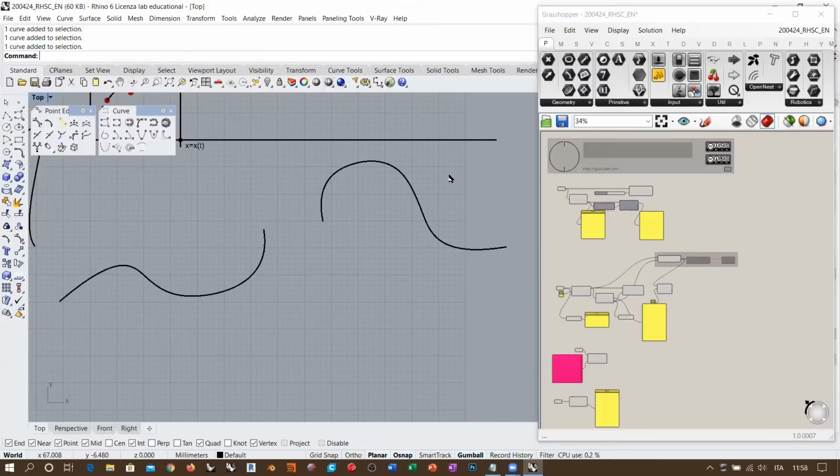If G1 is basically defining the direction, which is tangency, then there is G2, which is curvature, and then there are G3, G4, G5, and you can go up to G whatever you want if you think about it, okay? Because as long as your equation allows first, second, third, fourth, fifth degree derivatives, then you can go on and on and on and calculate this new function, okay?